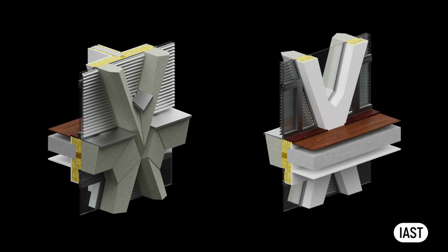However, if the louvers are proven to be suitable to act as a barrier, the restrictor to the window may not be required. Having said that, it is best to make provision for the restrictor, at least at the initial design stages. Most of the hotels have restrictors installed on the windows, even if the vents are above 1100 mm level.